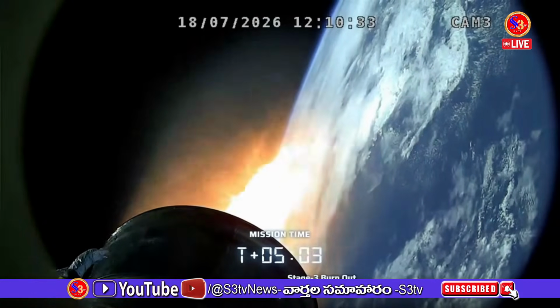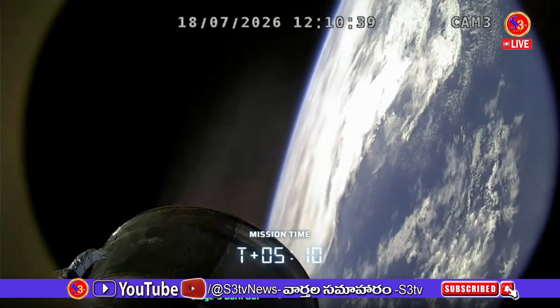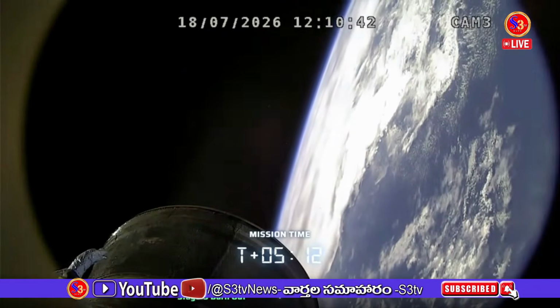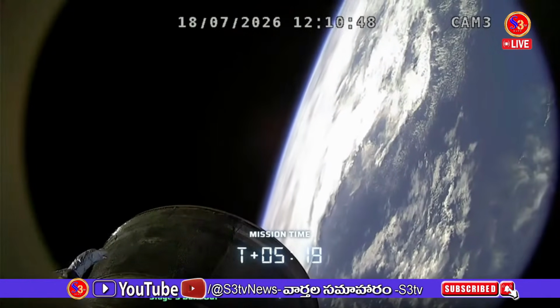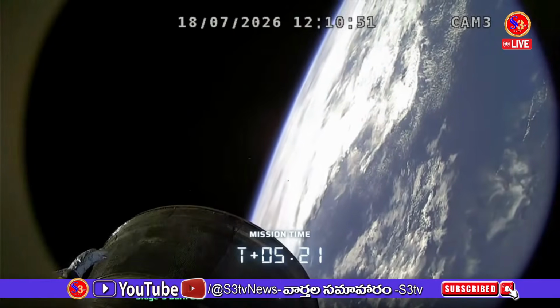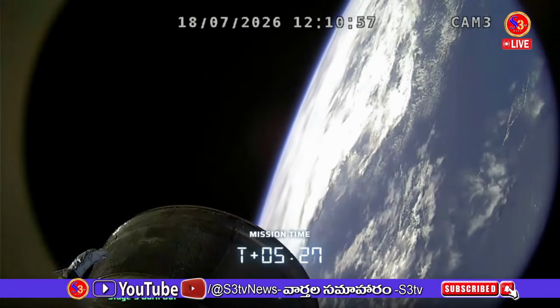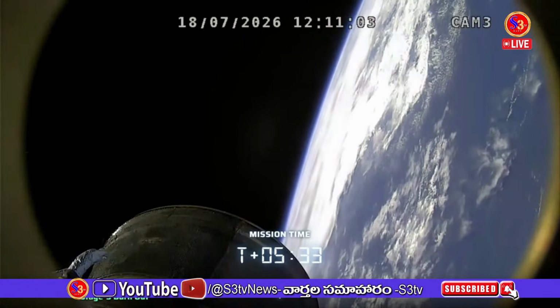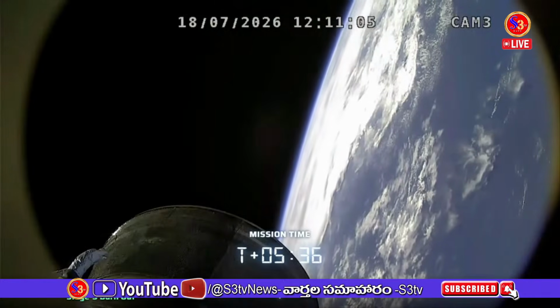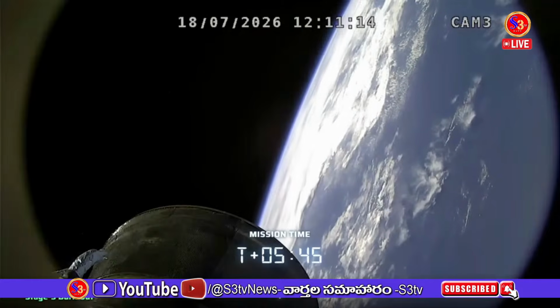So stage 3 has a propellant loading of 2.5 tons, and we've had burnout of the stage 3 motor as planned at S3 T plus 5 minutes. Yes, we've gotten confirmation that S3 has burnt out, and now we're entering a planned coast period, something that lasts for 140 seconds, which is called the combined coast. Combined coasting is normal. Right, so we've got call out that the combined coast is nominal. This will last for roughly 140 seconds, where stage 3 is not producing thrust, but it's connected to the vehicle and it's going to coast as a single body.